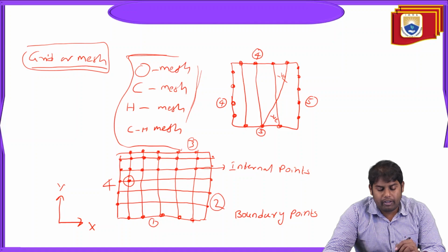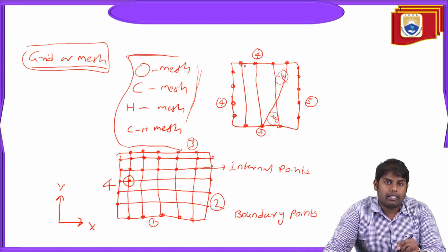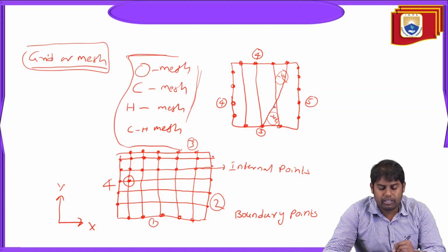But here, when we take an unequal number of grid points or boundary points along the opposite faces, what happens is that this grid point does not have any other point to generate the y grid line, so it will go somewhere and form a surface called negative faces or negative volumes. What I am talking about is purely for a structured mesh, not unstructured mesh. For unstructured mesh, this can be accepted, because it can have different types of faces or shapes. In structured mesh, this is not acceptable. Even in unstructured mesh you have some negative volumes, but it will take care of itself.